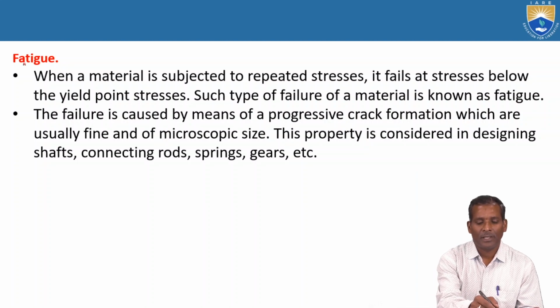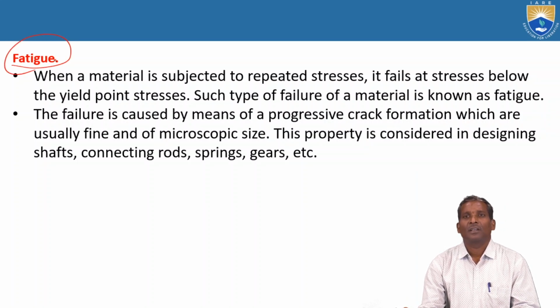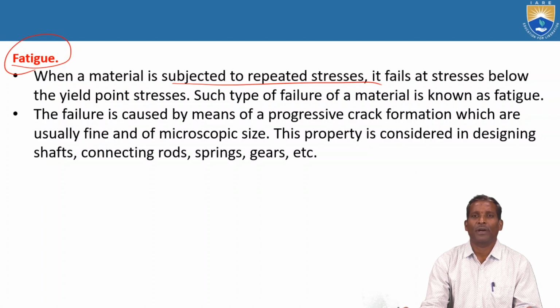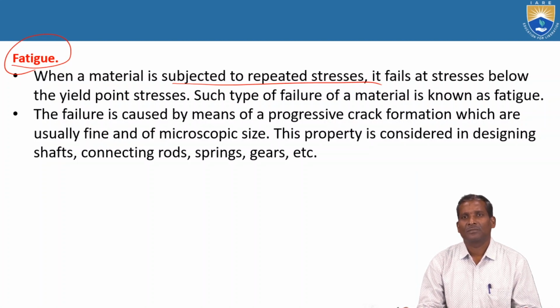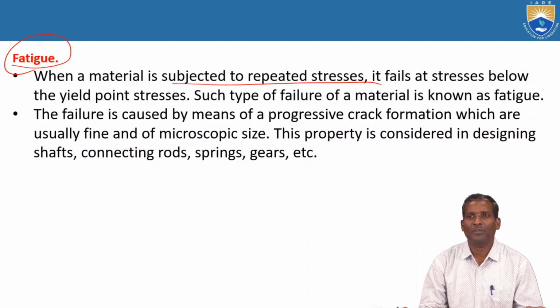Next, the fatigue property, which is very, very important. Whenever the material or component is subjected to repeated stresses, repeated cyclic loads, it fails at stresses below the yield point stress. Whenever the stresses occur below the yield point, the component will fail after a number of cycles. This type of failure is called the fatigue phenomenon.